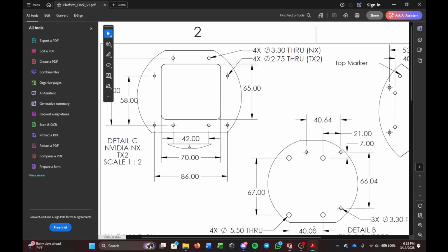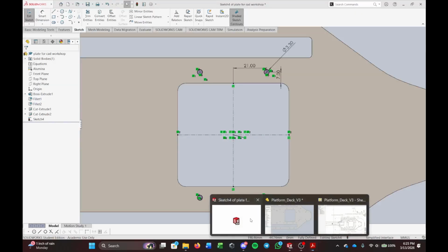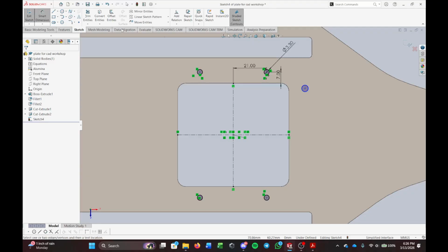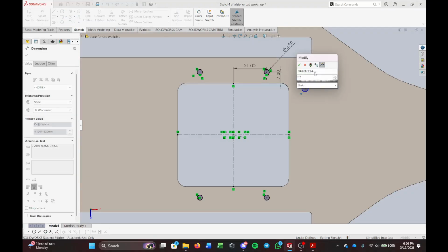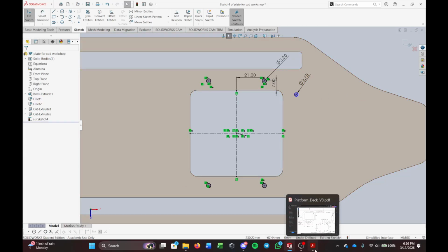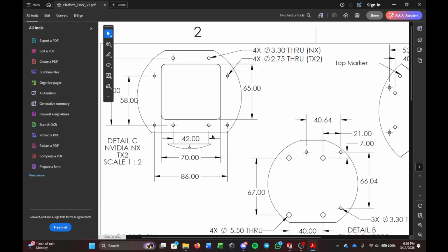All right, so let's double tap the document here. So it tells me there's 4 holes that have a diameter of 2.75. So that has to be each of these that are common. So 1, 2, 3, and 4. We're gonna go ahead and grab that. Drop a circle over here. Dimension that to 2.75, like so. Head back to my document here. See if I have information.